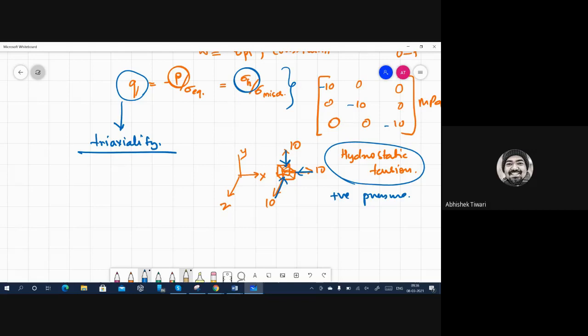So this quantity basically means how much hydrostatic stress component is there in comparison to the shear stresses. So that represents triaxiality, and damage parameter is a function of these two mostly. So for ductile metallic crystalline materials, we can define damage in terms of equivalent plastic strain rate and triaxiality.